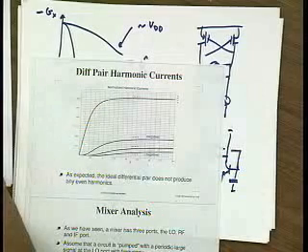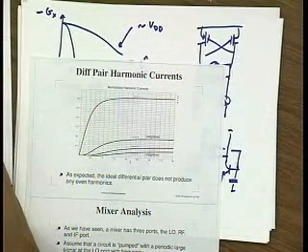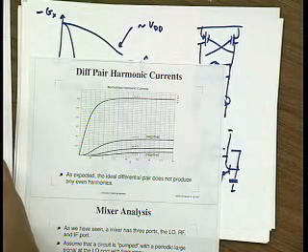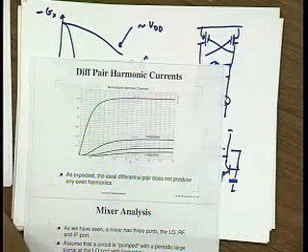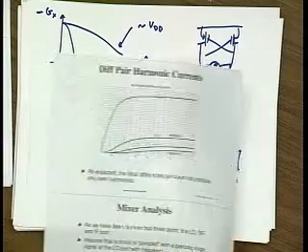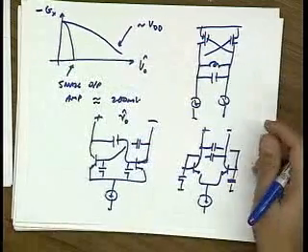Whereas with the bipolar device, we noted that if you build an oscillator from a single transistor, it won't compress unless we limit its current. Okay? So that's an important difference between differential oscillators and single-ended oscillators.